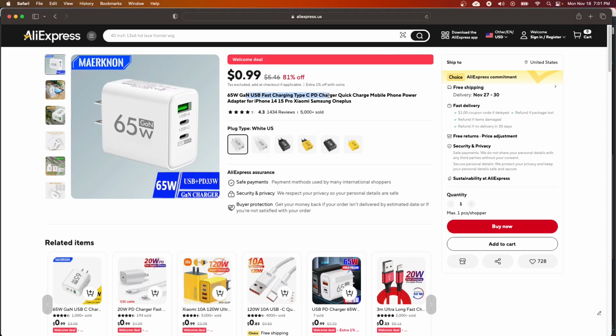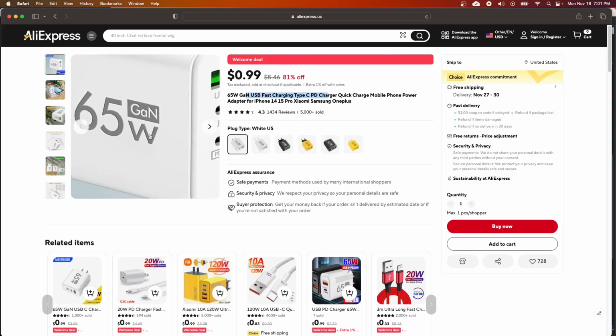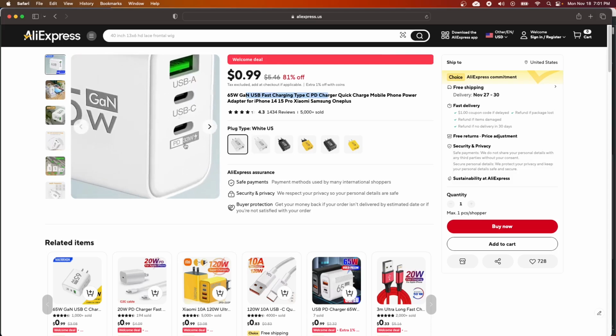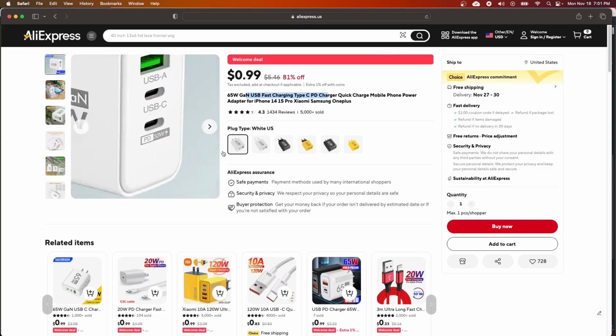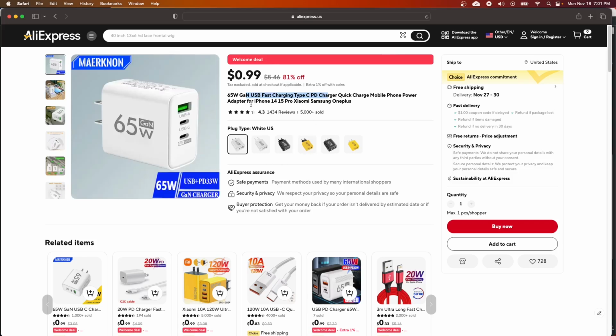Okay, so I assume there's going to be a way for it to do the PD power delivery negotiation. And I assume that there'd be a chip in there and that it at least could put 33 watts out there. So I bought this adapter, and the first thing I did was try to get some negotiation going so I could get the 12 volts or 15 volts out of this adapter. And let me show you what I've got.